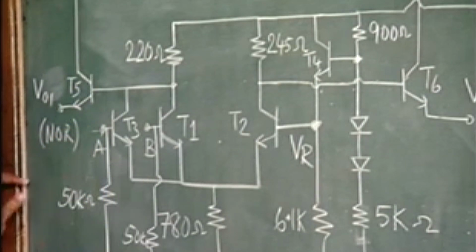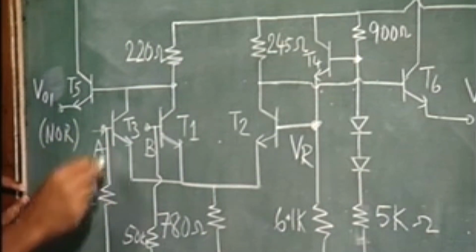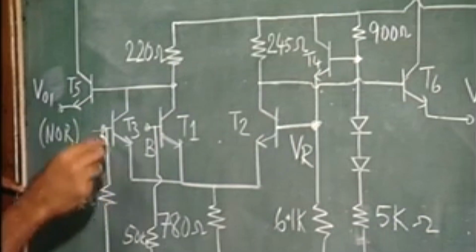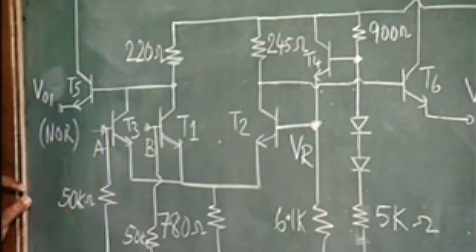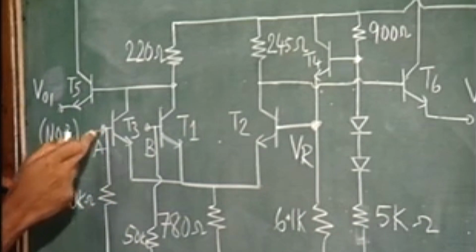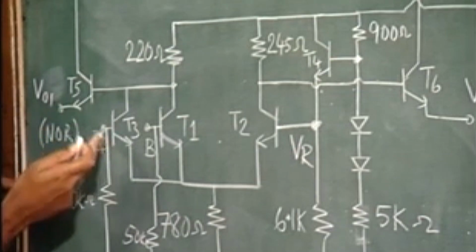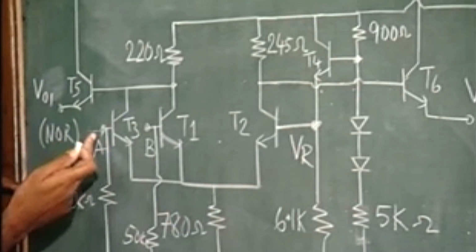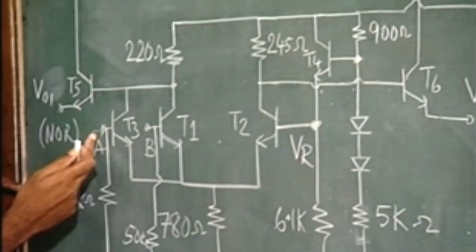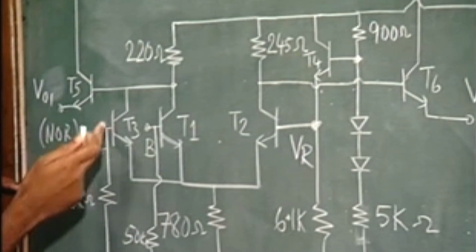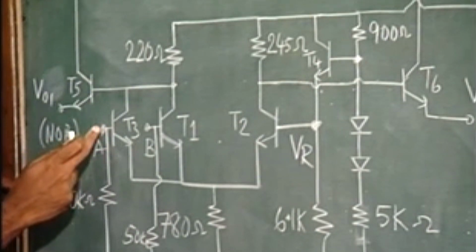Why you have a resistance here at the input is, one reason is that the base is basically connected to the lower potential. So, if any input is left floating, it will be a low voltage, a logic 0 at the input.